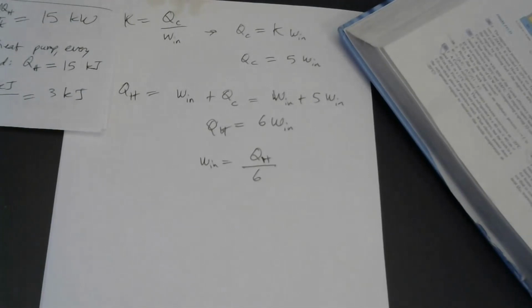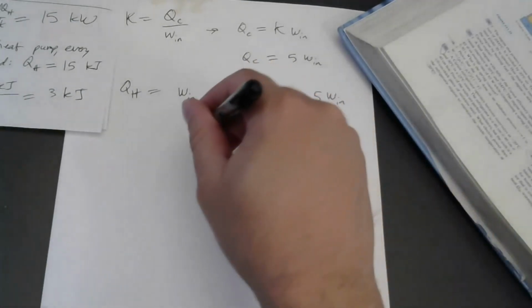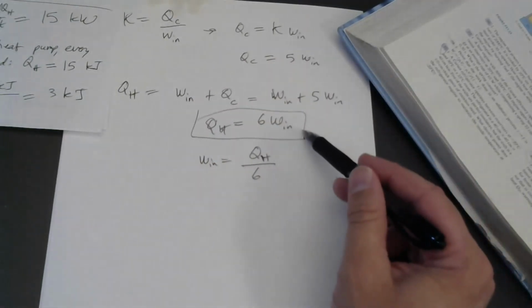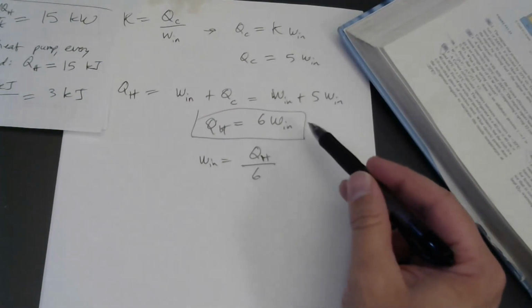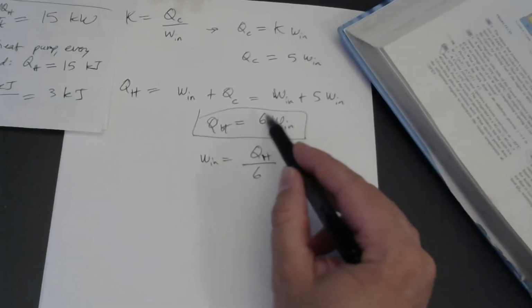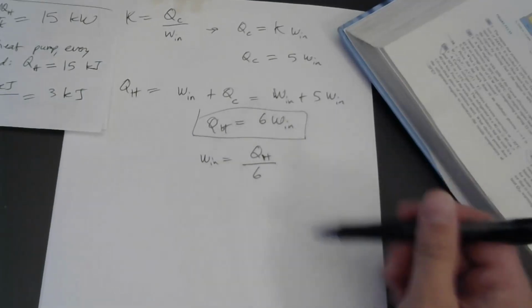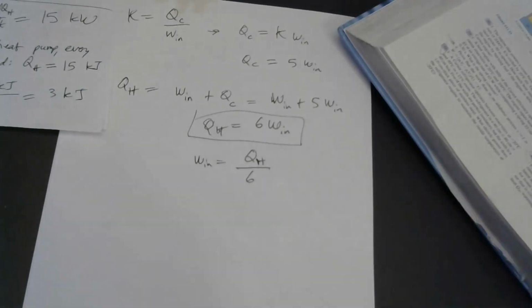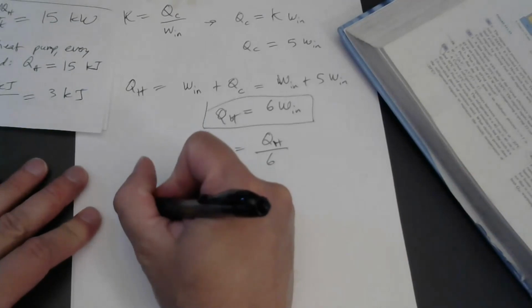I know it seems like we're going around in circles here, but this ratio really defines the coefficient of performance for a heat pump. And the way your book defined in the problem coefficient of performance for a heat pump was this. And they said that this is 5. Does this make sense? The confusion here comes from the two slightly different definitions of coefficient of performance.